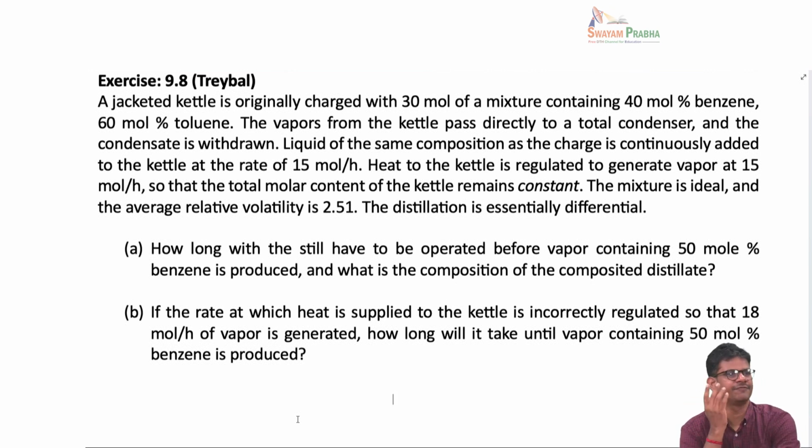So how is this problem different from any of the previous batch distillation problems? Feed is, yes. So operationally, generally if you think about batch distillation or differential distillation, you start with an initial liquid mixture, and then you continue to vaporize. So as a function of time, the amount of liquid in the still will decrease, to the extent that you are vaporizing it.